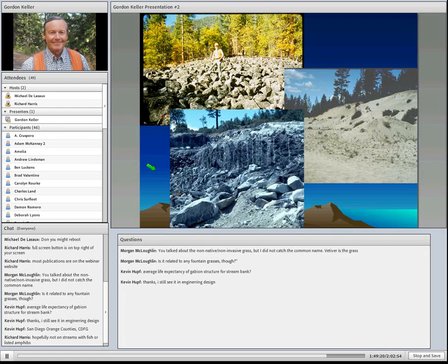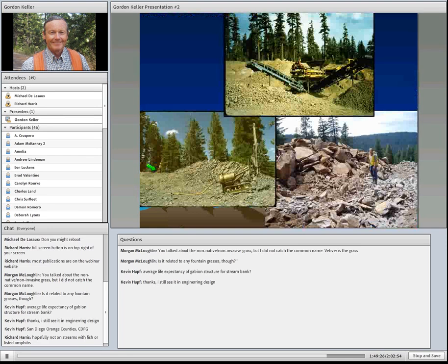Part of it depends on finding what's available and then how you develop it. A lot of development issues, the space issue. Can you get away with just screening? Do you need a 2 or 3 stage crusher? Do you need drilling and shooting in the first place? Will it come out okay if you have a good shot, oversized material versus a broken down material, depending on what you want? So those are kind of operational issues.